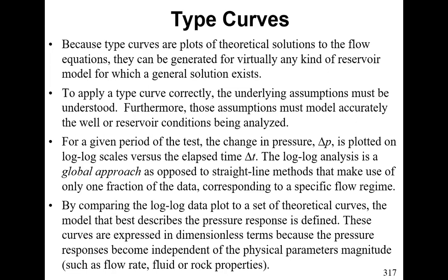Once you can obtain an analytical solution to a particular diffusivity equation, type curves can be produced for that reservoir system, and then all you need to do is to superimpose your own test data on the type curve and look for a match. For a given period of the test, the change in pressure, that's delta P, is plotted on log scales versus the elapsed change in time.